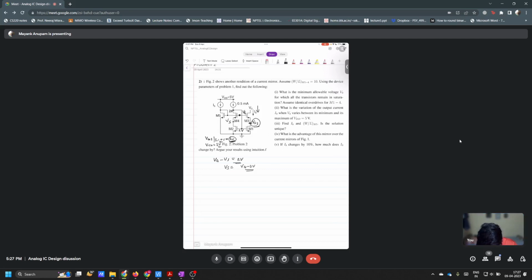Sir, VDS equals VGS minus VT, no, sir? That is for the transistor to remain at the edge of saturation. Sir, VS will be constant, no, sir? Then VD equals VG minus VT. So VT will be independent of VS, no, sir? Oh, I understand your concern. True, but you do not know what VG is at this point, right?